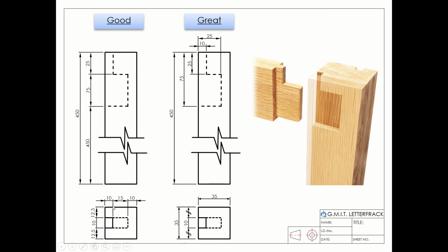If we take these dimensions here and move them up here, I've given chain dimensioning, like so. So chain dimensioning versus our datum dimensioning. You can see these are one after the other, whereas these ones each come back to a single reference point. Which is better, which is best there? Well, it depends on how you manufacture the piece.